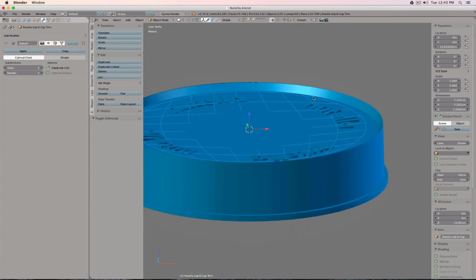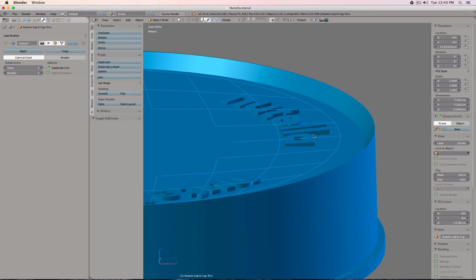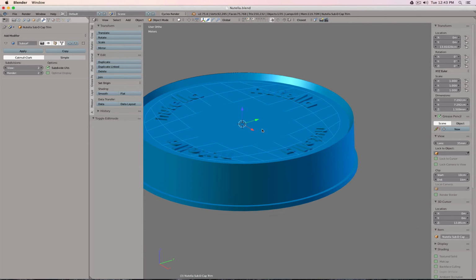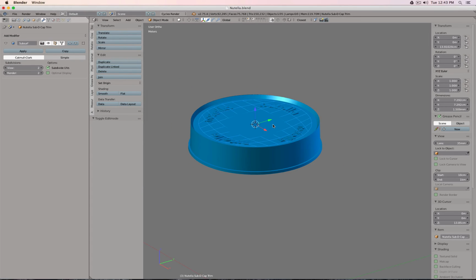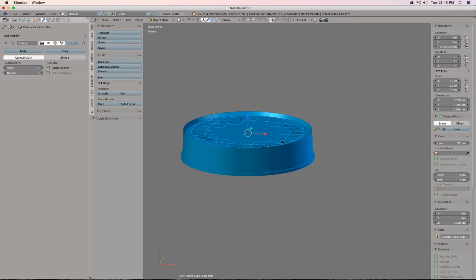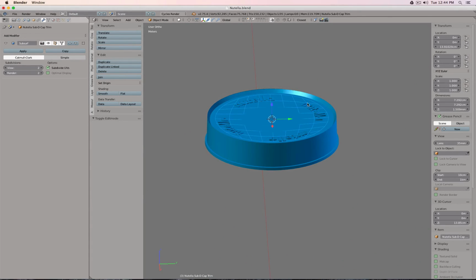Okay. And you see actually now that the letters are not linearly capped to the center. They get thinner, to the outside they get taller. So that's for example the reason why I took the time to redraw one logo with the sub-D outline extruded into a vertical shell, because then with a cap surface I can trim it, or trim it and at the same time sculpt, for example, a certain design. And because everything here, the letters are in a circular array, I can create kind of like a half dome shape and then change the way how the letters look.